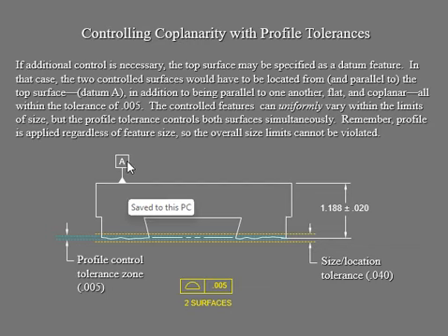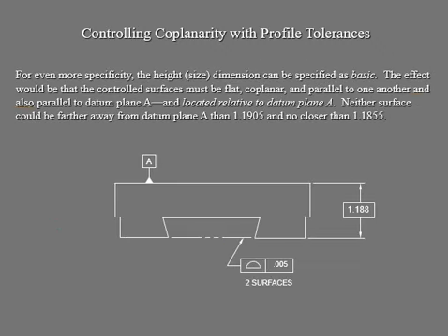So your datum reference is right here. So when you do the verification, that's where you will look at the parallelism for the top surface with your two control surfaces right here, because they are parallel anyway. So don't forget these little things. But to simplify, the whole thing is it's got to be in your tolerance zone. That's all. It can't go outside of it. As long as you're in, then you're safe.